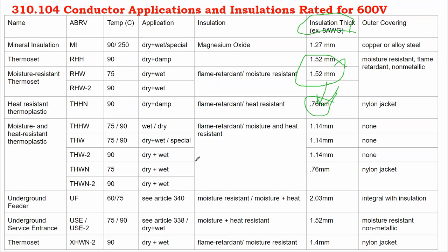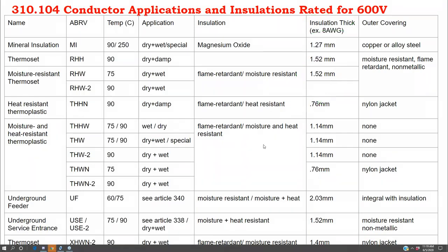And furthermore, it's that thicker cable jacket inside that conduit is going to retain heat in the cable a little bit better. So by and large, you want to use indoor cable inside and you want to use outdoor cable outside. Maybe for a very short run, sure.